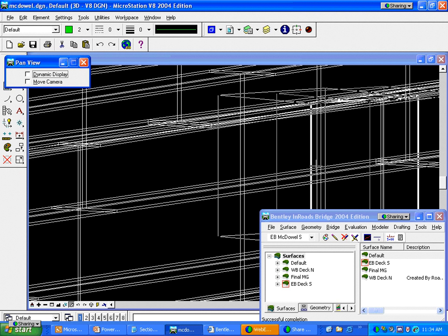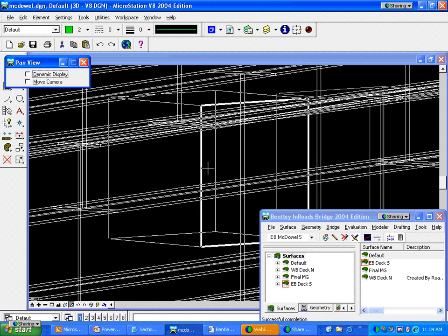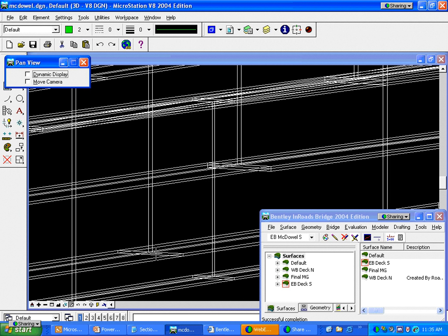Then in the interior girders, you can see the bottom of their sections. And you can see right in the middle of the screen there, I have a bottom flange, and it's also drawn my bottom cover there when it's extruded that. So I can see that that station right there on that girder is where the beginning of that bottom plate is. So we can see that it's drawn it correctly there.